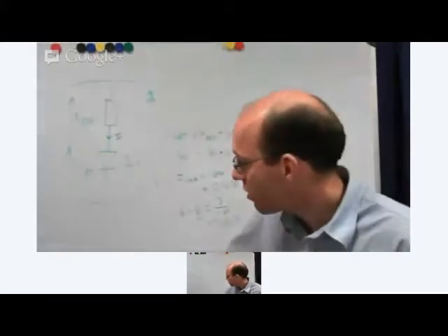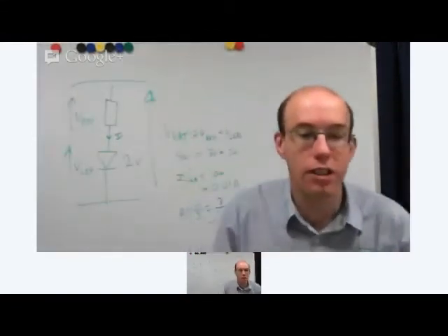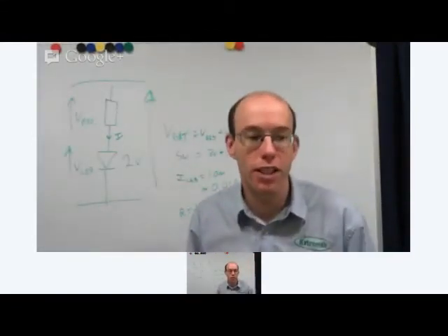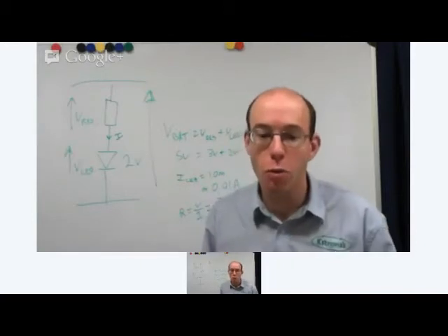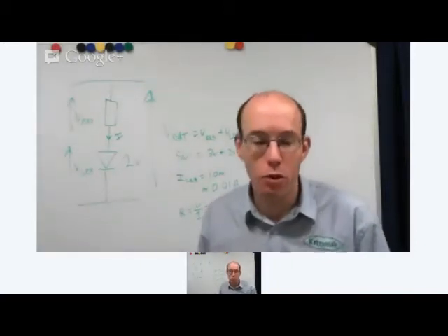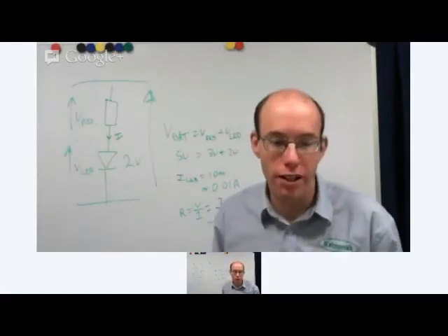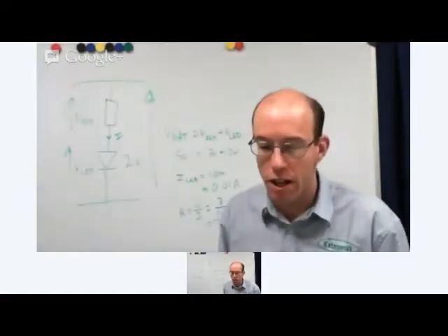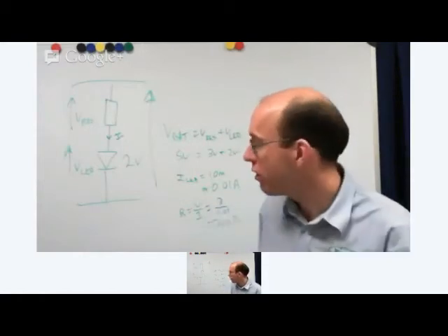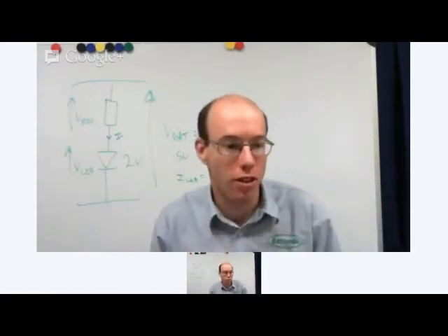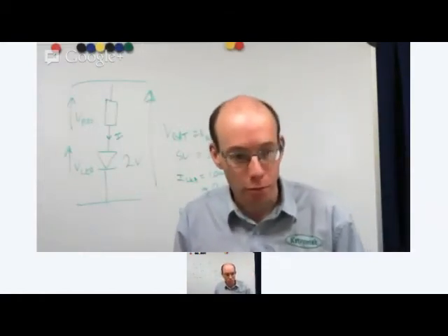If you don't want to do that yourself, then we have an LED resistor calculator. On all the product pages that have got an LED on them, there will be this resistor calculator. You plug in the battery voltage, it already knows what LED you want it to be, and you just click calculate, and it will also tell you what the resistor colour bands are that you need to go with that.